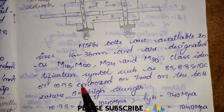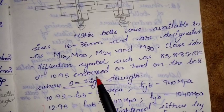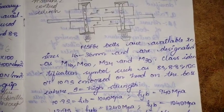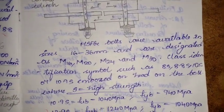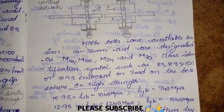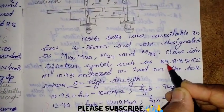The class identification symbol is 8S, 8.8S, 10S, embossed on the head of the bolt, showing which class it belongs to. The S represents high strength.